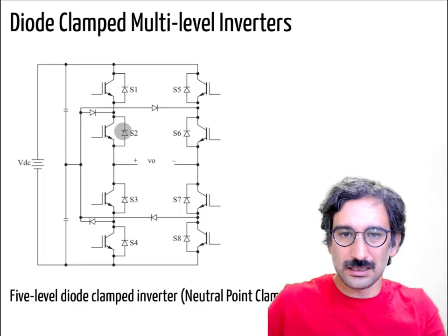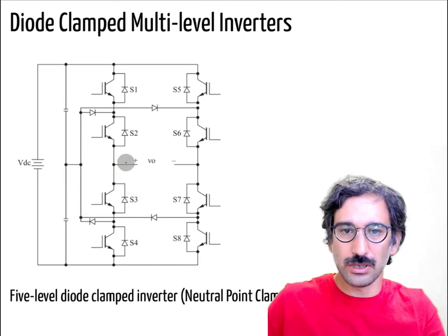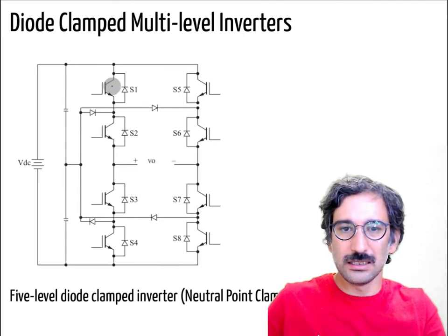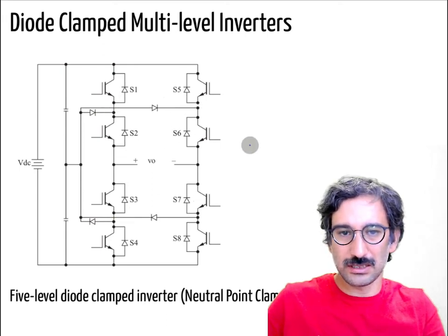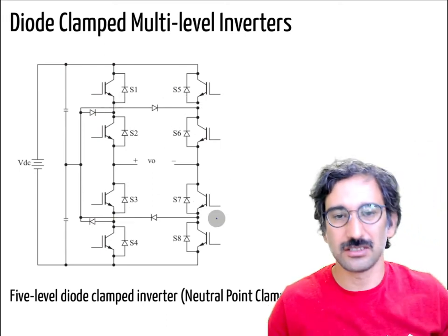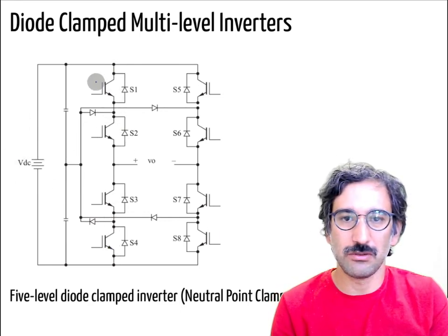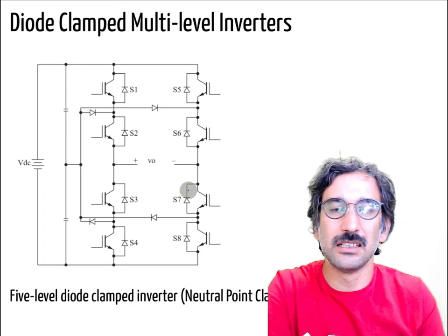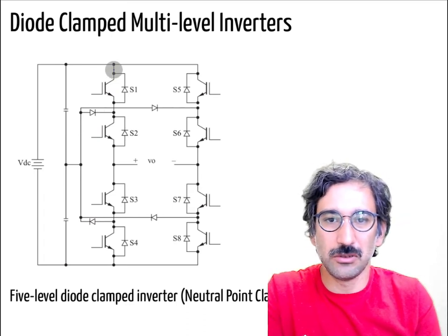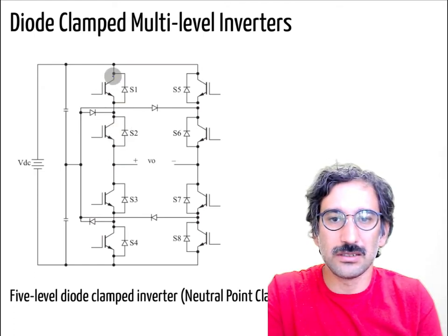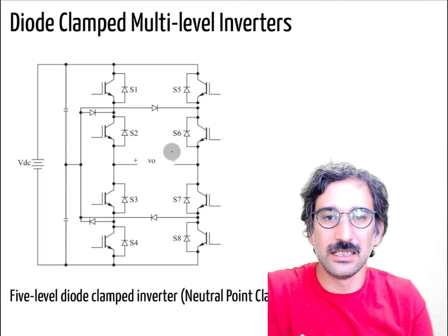So the idea is like that. Again, you can see the half bridge, like a normal H-bridge structure, as we have the VDC voltage. If you just look at those ones and those ones, and think of those things as single transistors, it seems like a normal H-bridge. But instead of connecting just one transistor, I connected two transistors in series at each place. So I have 1, 2, 3, 4, 5, 6, 7, 8 transistors.